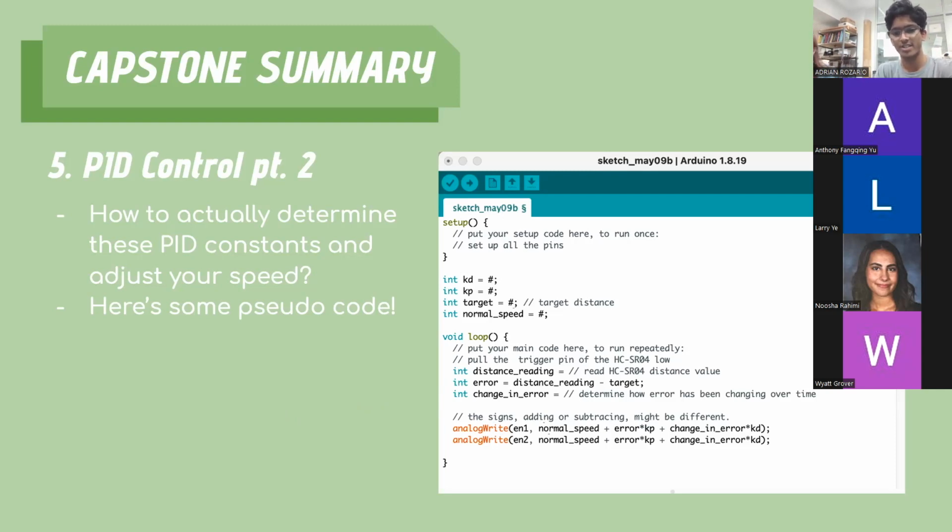That's when you add to the speed of the motors. It's different if you move your hand closer, so your car might slow down and eventually back up. Those are all parameters you'll need to set up. Again, you'll need to experiment to see what each of the thresholds should be and what your KD and KP will be. They'll be different for everyone.